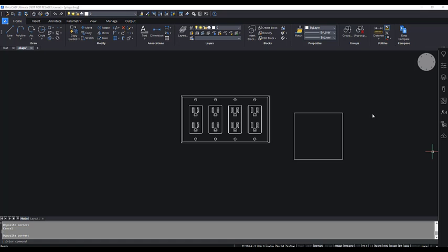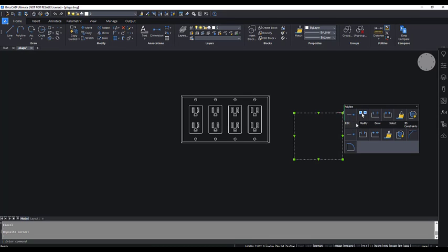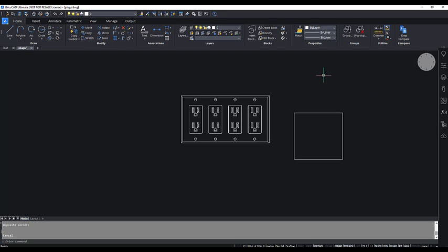The next interface element would come up when you want to modify an object. This is called the quad display. It actually will pop up if you just hover over an entity. This has some submenus, but unlike most right-click menus, this just has icons. They're nice and large. If you don't like this interface after giving it a try, you can always disable it, and then you will have access to the right-click menu that you're more familiar with.